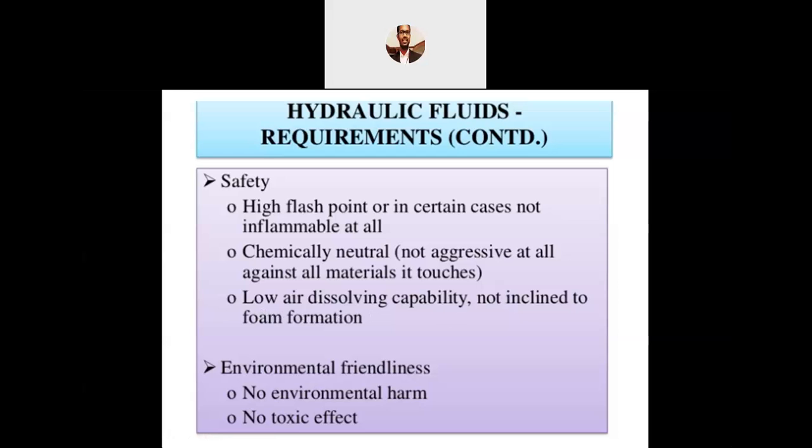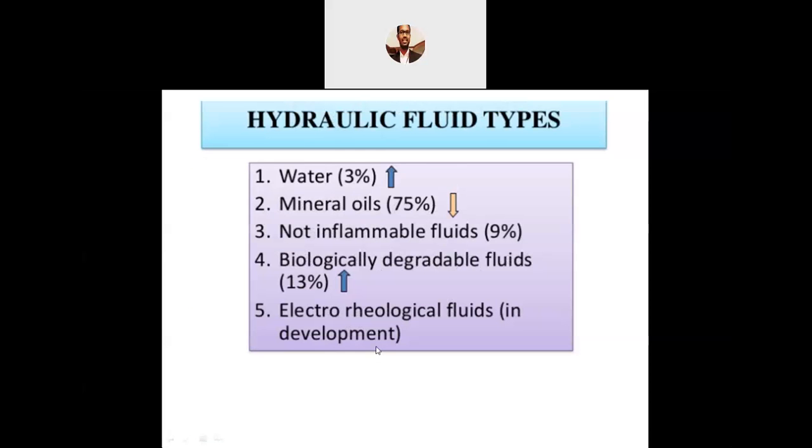Foam formation should not happen. Foam means what happens when you apply soap and rub it in your hands, foam comes, that should not be the case. Next one is environmental friendliness. It should not be environmentally harmful, and there should not be a toxic effect. Okay, these are all the requirements of hydraulic fluid.